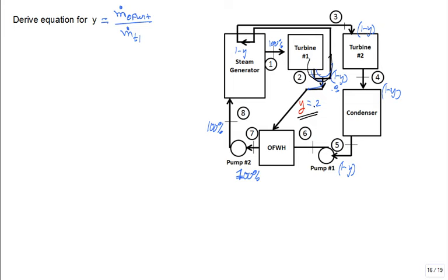Well, we know the pressures. Didn't we talk about the pressures already? What is the pressure at 6? What is the pressure at 2? What is the pressure at 7? It's all that intermediate pressure. Think about 1 MPa, that intermediate pressure, okay? How high can the energy content or the temperature at 7 be? Because I want to boost that. That's getting into the pump, into the steam generator. What is the maximum temperature at state 7?